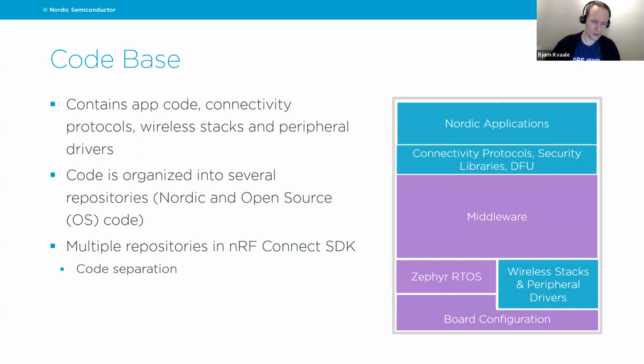So we do have multiple repositories in nRF Connect SDK, and this does create a nice code separation. So we do, for example, use the Zephyr repository, but we sort of make our own clone of the Zephyr repository, which means that if there were to be some kind of breaking changes in the code in the Zephyr repository, our clone of the Zephyr repository would not see that. So it's very useful to have multiple repositories, especially when working with open source code.